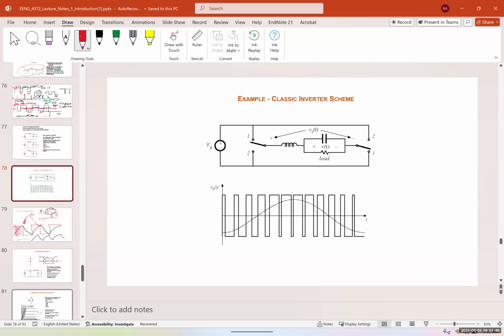And this is exactly what we have here. So in this example, it's 90% negative, for example, 10% positive. And then the average would be around here. And then for the next one, it's going to be a little bit less negative. And then you can see that we can create something that is very close to sinusoid.